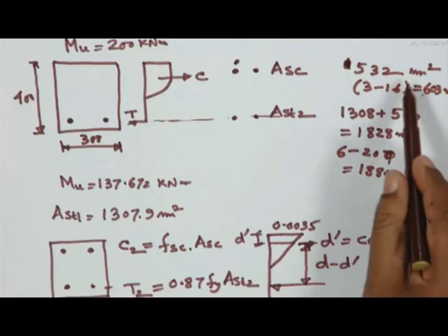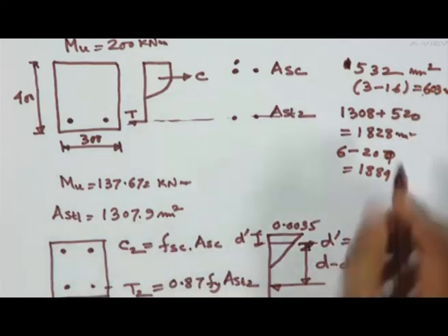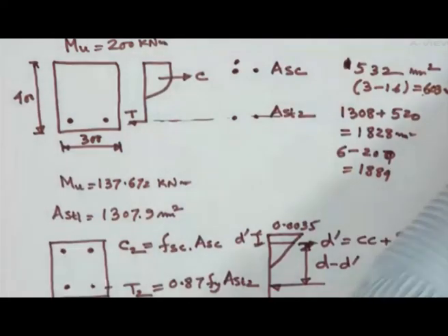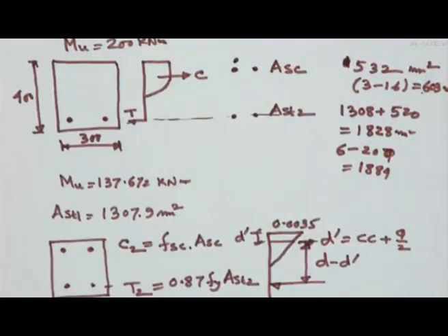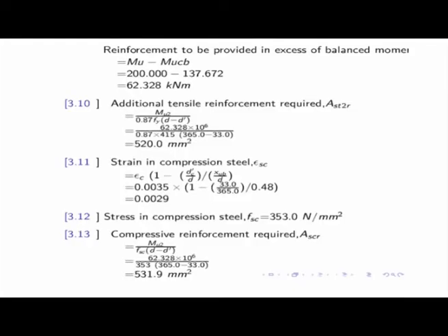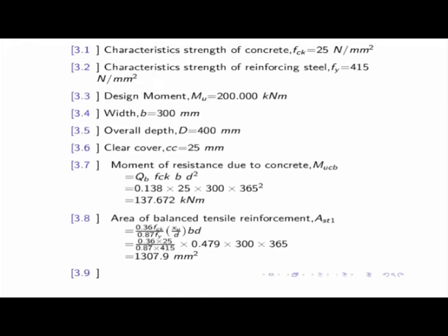So this is the one that we do. Please note this once more. I am trying to tell you that in your doubly reinforced section, just to recapitulate, first you have to calculate the bending moment for the balanced section, how much it can take, and what is the corresponding steel that you have to find out.